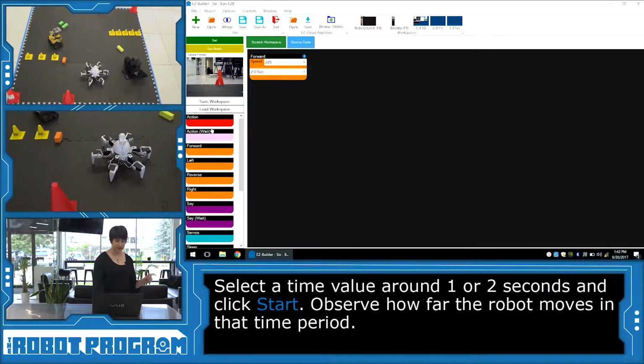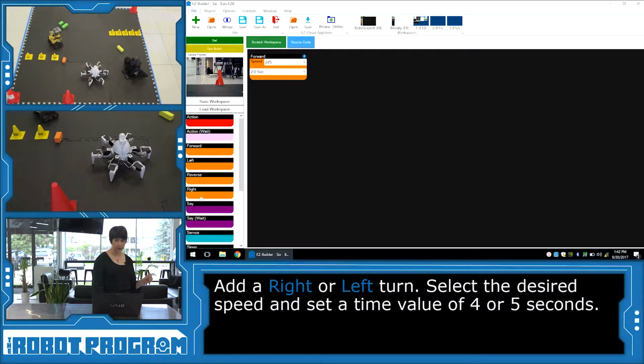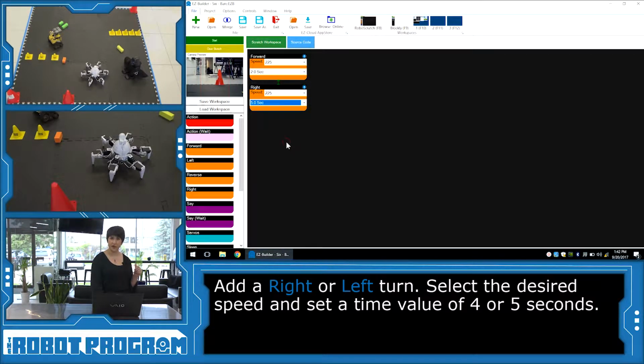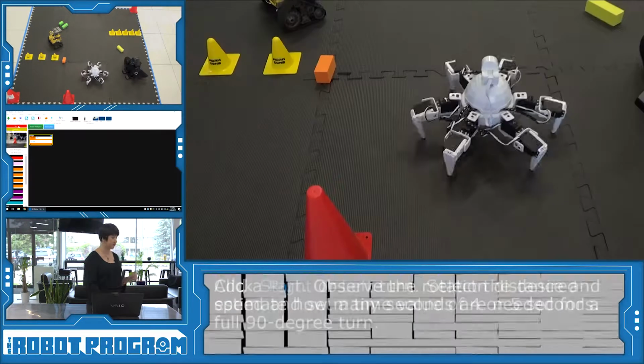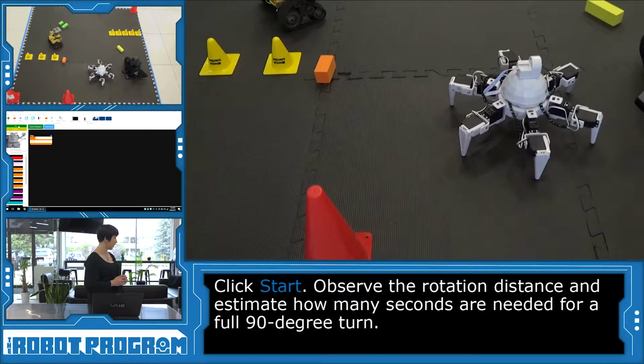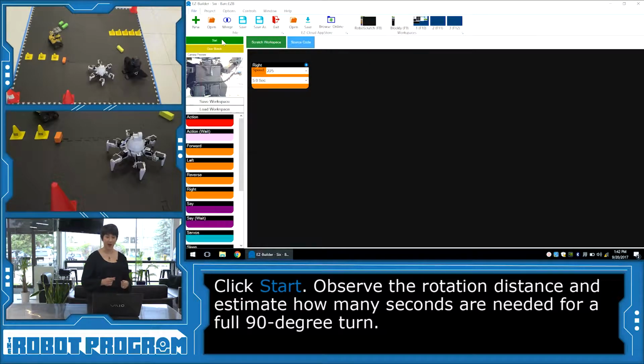All right, now let's see if he turns right. How long does it take him to do a 90-degree turn? So again, I want to go about 225. And I'm going to guess around 5 seconds. So let's delete the forward code. So all we're going to do is move right. So he's facing forward, and I'm going to click Start. Let's see how many degrees he can get around. Perfect. So at the speed of 225, it takes Six about 5 seconds to do a 90-degree turn.